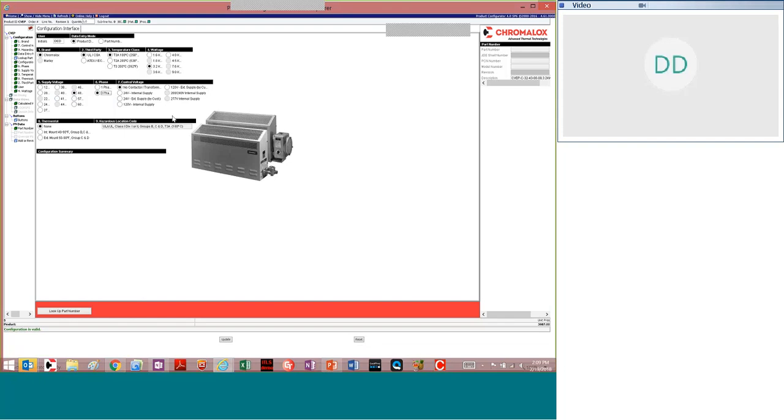So in the case of a customer providing a control signal, if we don't supply it with the ability to understand that and to switch based on a 24 volt signal, they're going to be in trouble. We're giving them the wrong product. It is as simple as just asking them, what is your control circuit? Is it 120? Is it, in some cases, 240? And that's going to be true for all of our products, and it actually correlates over to our heat trace as well.